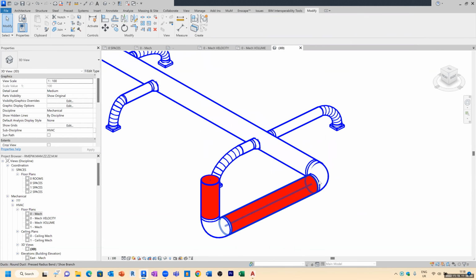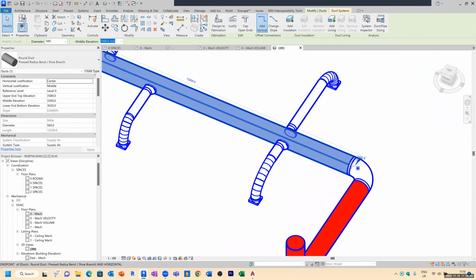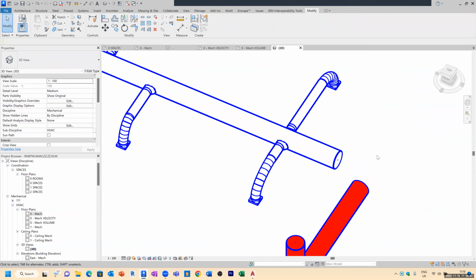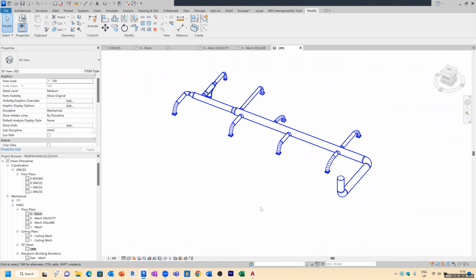You can see there's no flow coming through this fitting, and actually going through here, you can see now that's not actually connected properly. So let's pull this back. Let's delete that bend, and then let's connect this to this. Now we have our flow again.